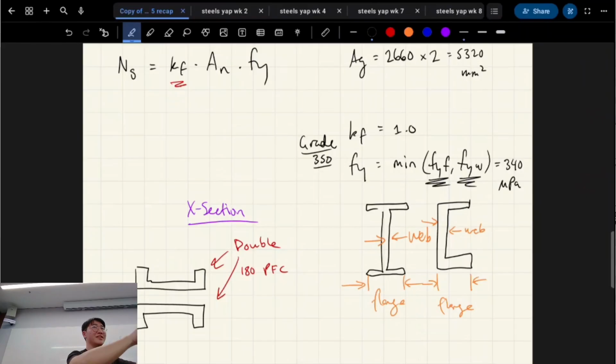Probably not, right? So that's the idea: when you have something that's thinner, it's going to have a more consistent yield strength. You have something thick like that, its yield strength can be poor because it didn't cool properly, basically, right? And so that's where you get differences based on the thickness. So the thickness of the flange and the thickness of the web are different. Got it?